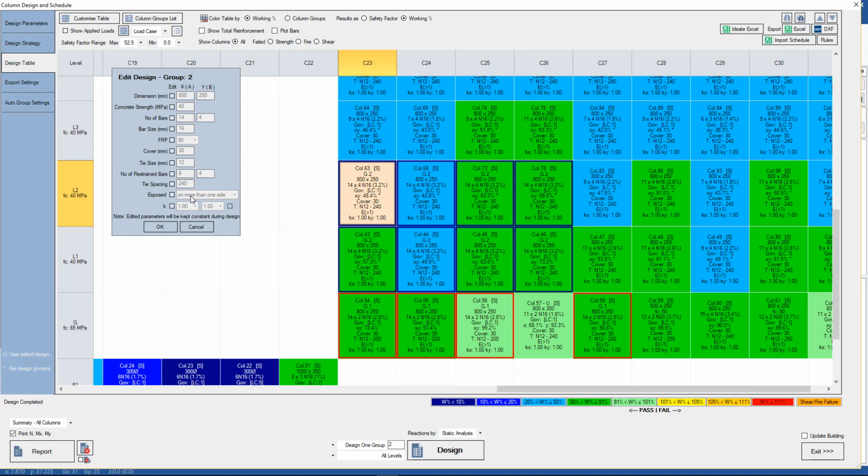As the design progresses, if we don't want to lose any design results, for argument's sake, say we're happy with the bar size N16 that was designed for this particular column and we don't want to lose it, we lock in this value by hitting the Edit checkbox. With this edit ticked, this value of N16 is locked in and will not be changed by the software.